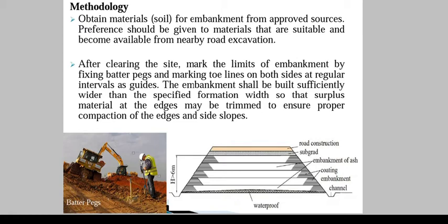And we have discussed the important elements with respect to embankment: its height, fill material, the settlement, stability of foundation, and the stability of slope. Stability of slope is very important as the height increases.